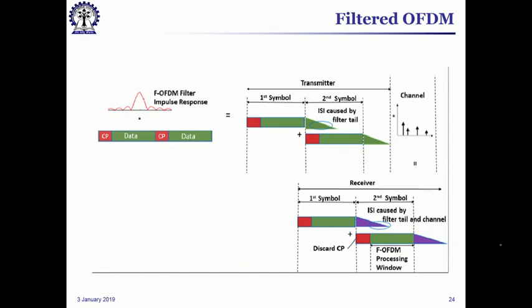Typically any OFDM system, I mean probably this I had mentioned earlier also, is one where one considers a rectangular pulse shape. But if you take any commercial OFDM system and you look into the standards, you will find that, of course, this is the CP, that there is some kind of a windowing which naturally happens, without which you cannot generally send out the signal.